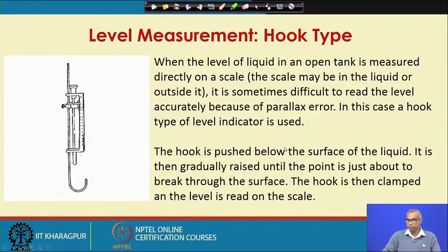The hook is pushed below the surface of the liquid. It is then gradually raised until the point is just about to break through the surface. The hook is then clamped and the level is read on the scale.